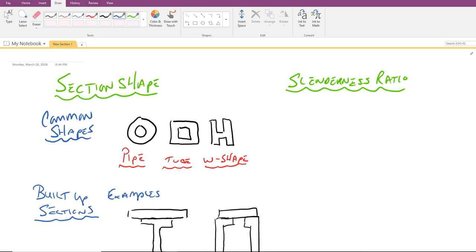We had the long columns on the right, the short columns on the left, and we tend to design our timber columns in that middle section where we have inelastic buckling. With steel columns, we only use two major breakdowns, and we actually take and lump the first two together. So we'd have short and intermediate columns, and we'd have long columns.